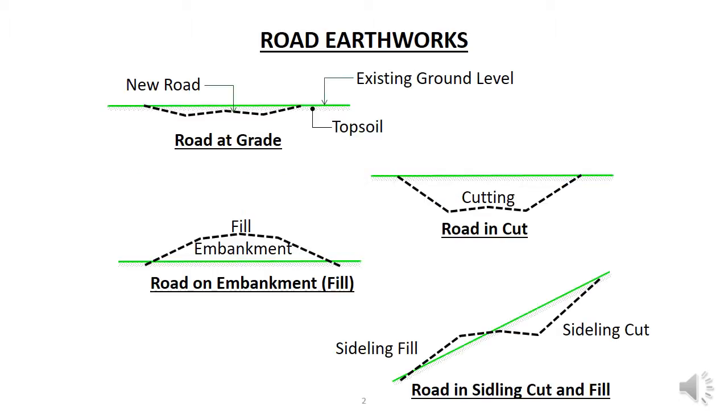In this video, we will look at the different types of earthworks that may be undertaken on a roading project. The road is supported by the existing soil or rock that underlies the road. If it deforms, then the road above also moves, which can result in the road not being usable or, in other words, it fails. Therefore, it is important that the underlying soil or rock can support the road without moving.